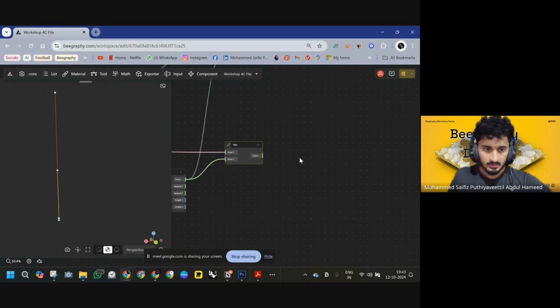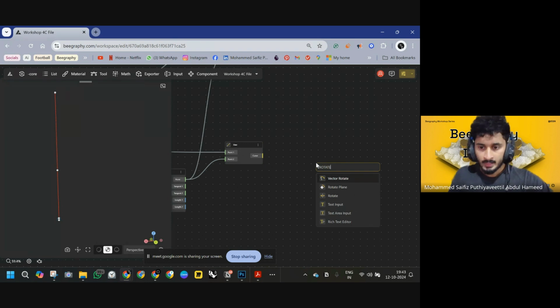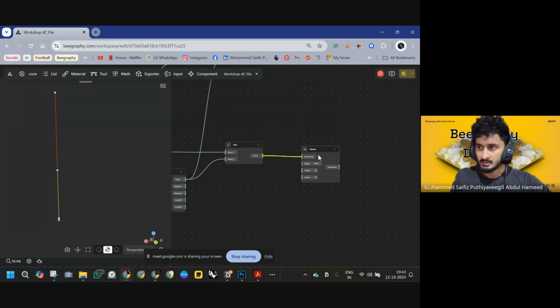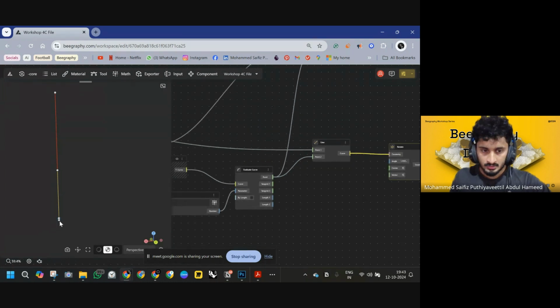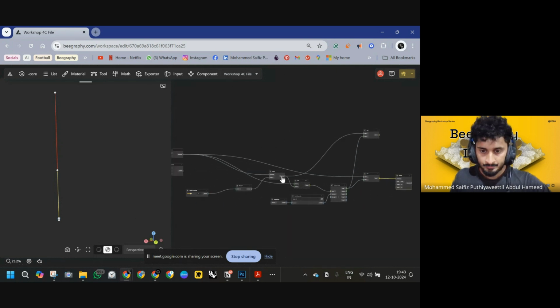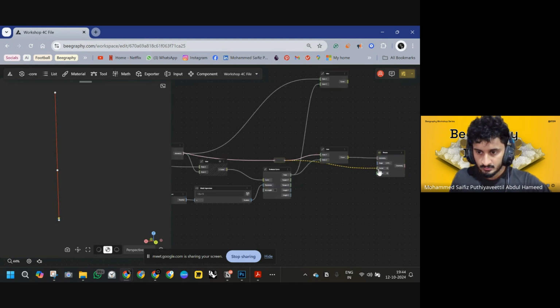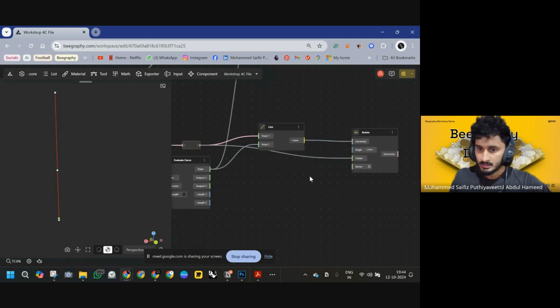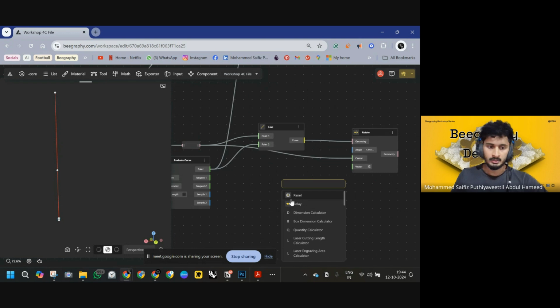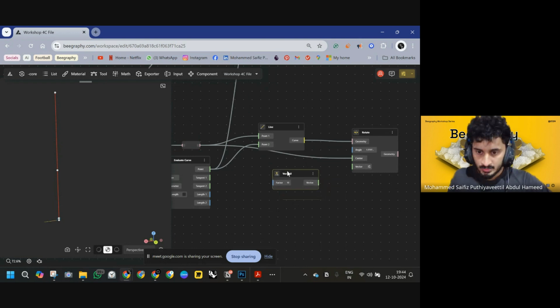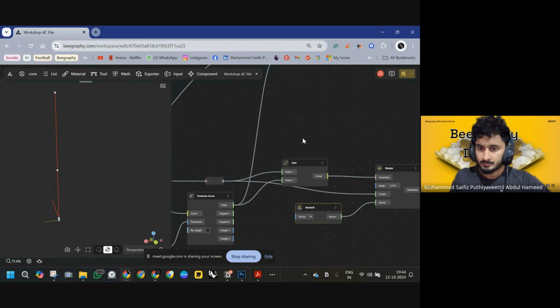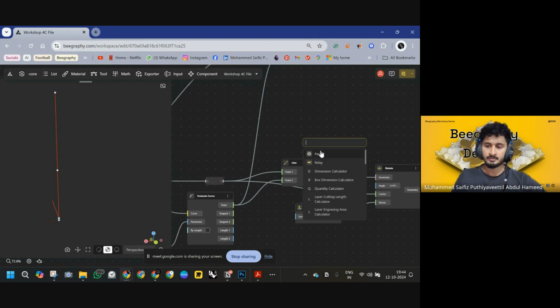What we'll do here is we'll take the bottom one, we'll rotate it at the base. This line, we'll use the center, this point, and we'll rotate it along x-axis. And then, yes, we need to provide an angle.